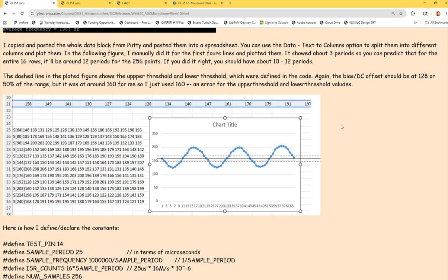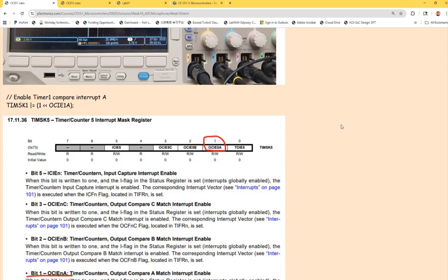But you know, I googled it. It says it's 2 to 4 kHz, which is fine. Okay. So if we choose 25 microseconds per sample in our code, what is the sampling rate? We did the calculation. It's just 1 over 25 microseconds, which will give you 40 kHz. And how many ADC clock cycles are required to finish one conversion? We talked about that on Friday. That was 13 cycles for the ADC we used here, right? So 13 cycles.